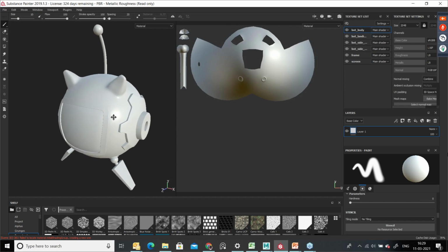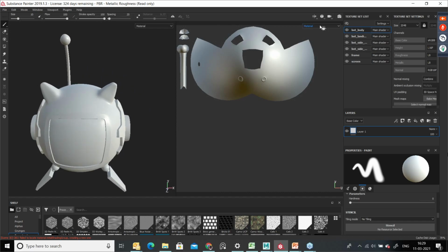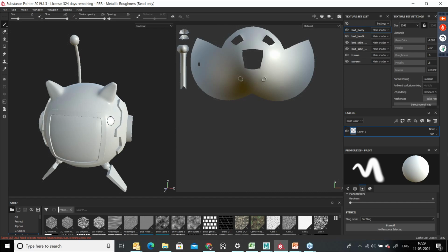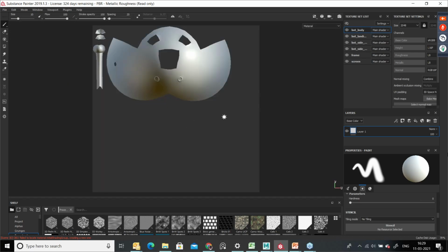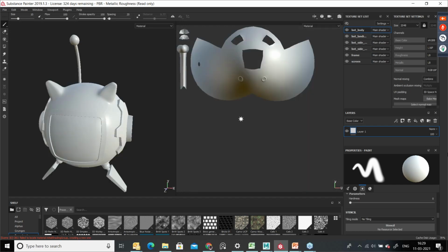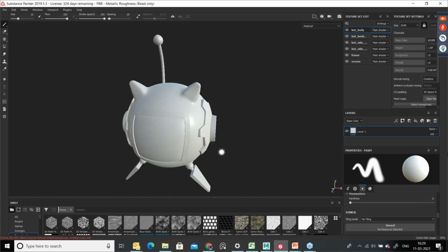Suppose here, this is a geometry. Now we can use the shortcut keys F1, F2, F3. When you press F2, only 3D; F3, only 2D; F1, both. Okay. So here we have a perspective view, and we have an orthographic view also. When you have a perspective view, your view will be perfect.